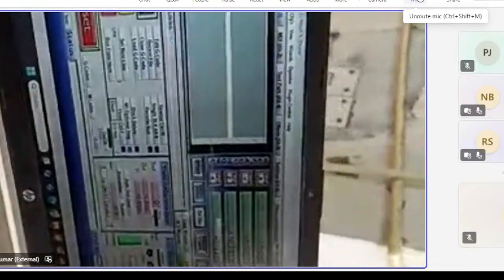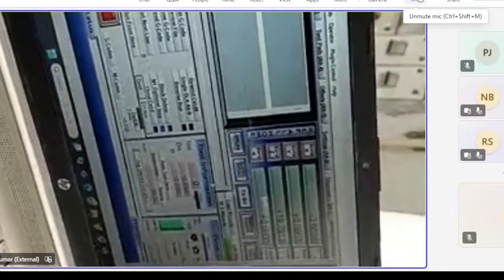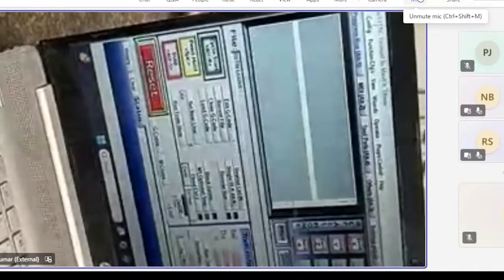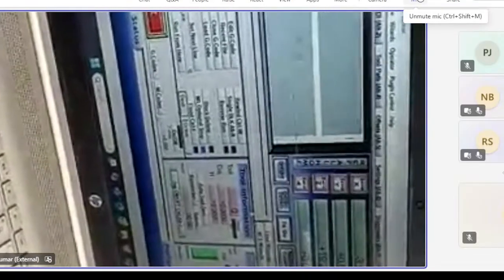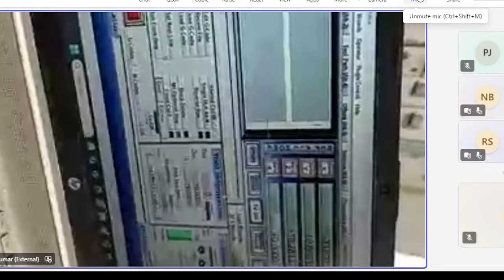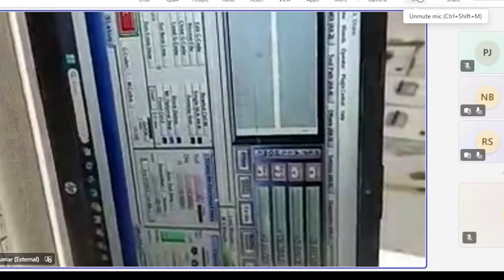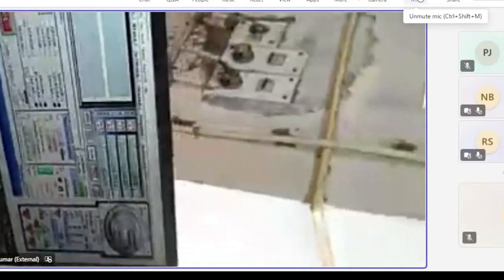Before starting the experiment, what we do initially, as I told you, is that for any additive manufacturing part that we want to deposit, we first create a CAD file. After that, we go for slicing, and after the slicing we generate the codes, that is the geometry code and miscellaneous code, G codes and M codes.